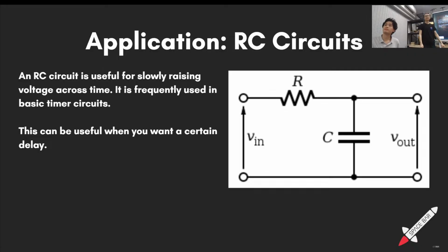Okay, so when does the capacitor discharge? The capacitor discharges into V out. In this case, the capacitor will not discharge until the circuit turns all the way off. If V in goes to 0, it will discharge. So basically, this applies a delay when you turn on. When you turn off, V in goes to 0, then it will start exponentially discharging. That will also delay the discharge, but usually when we turn off a circuit, we don't care what it's doing. Something like this.